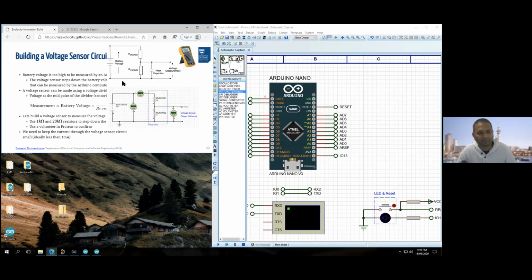So starting at the battery, positive 5 volts, when it gets round to the top of the resistor, no energy is lost, so it's still 5 volts there. Goes through the resistor, and if they're equal, it'll lose half that voltage in the top one, dropping from 5 to 2.5 at the middle, and then in the bottom one, it'll start off at 2.5 and drop down to 0 volts as it goes through the second one. Are you happy about that?